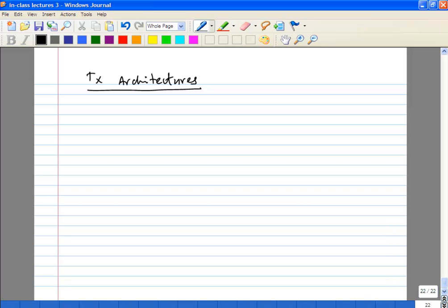But in reality it does. In reality your switch resistance is going to be a strong function of your LO voltage, for example. So that limits your IIP3. In the other case you are explicitly making it a function of your RF voltage. Because of that you can get much better IIP3s.